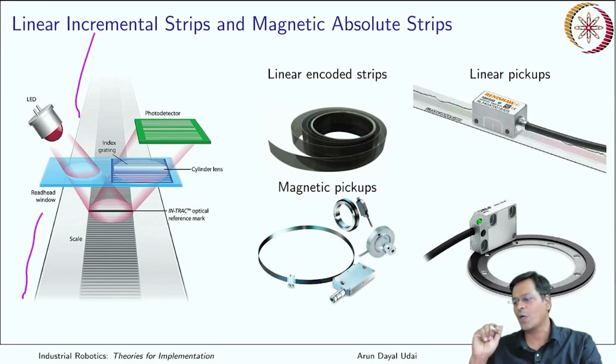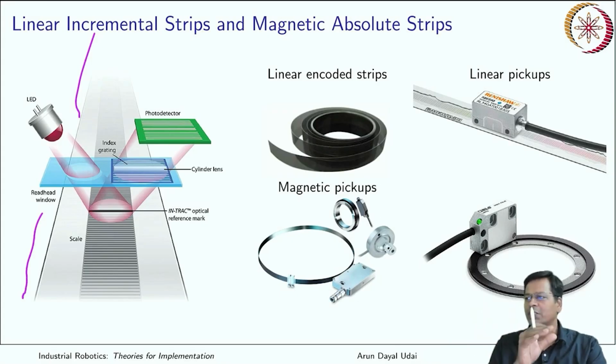It has a light that is thrown out, and it is thrown on the table on which you are swiping your mouse, and then the reflected picture is taken, and the change in that image is analyzed to find out which direction you are moving. So that is an optical sensor, non-contact, and it detects displacement, I tell you. So that is a very good displacement sensor that you can get off the shelf from your mouse. You can just pull it.